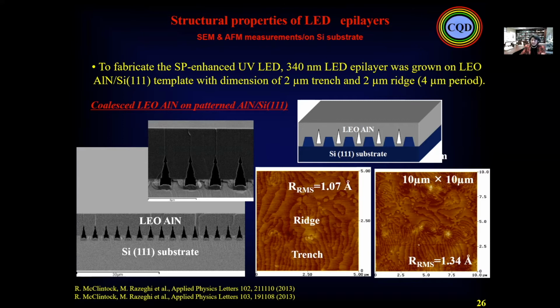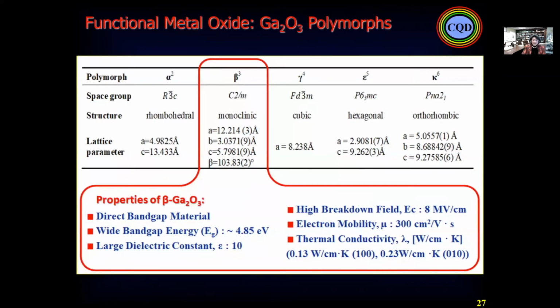So we developed the lateral epitaxial overgrowth of gallium nitride and aluminum nitride on silicon, and we demonstrated excellent LEDs and detectors on all of that at the same time, and that again is a very hot subject and is continuing. So now, as I explained to you, aluminum nitride can go up to 6 electron volts. But for this material, we do not have a lattice matched substrate.